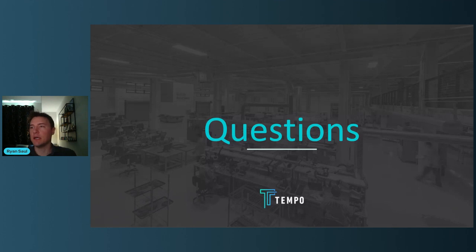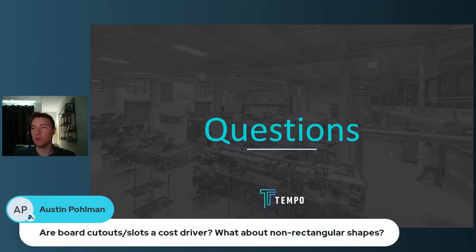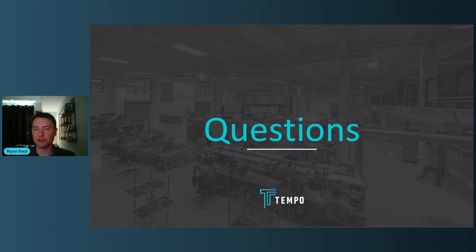Austin Pullman, again, asking, are board cutouts / slots a cost driver? What about non-rectangular shapes? Board cutouts and slots are not a very significant cost driver. Yes, you will add some cost, but it's not super significant. That said, you can design an expensive slot if you want.